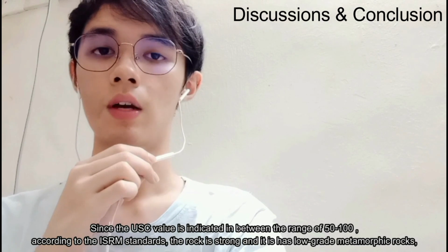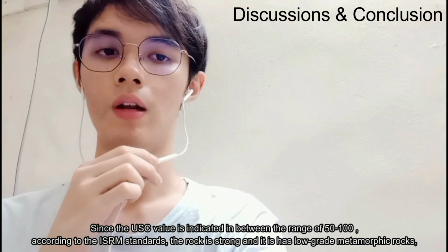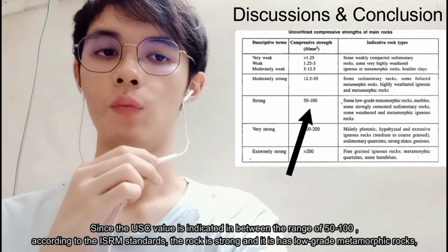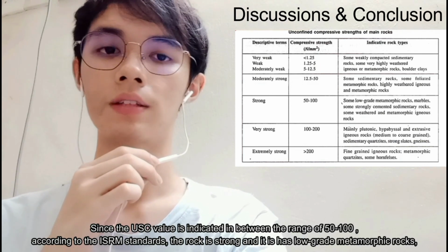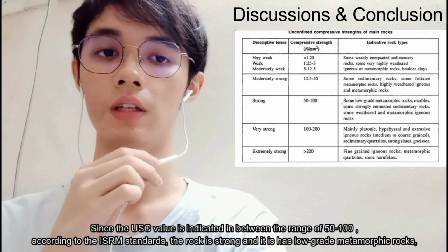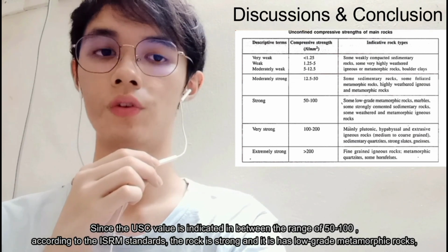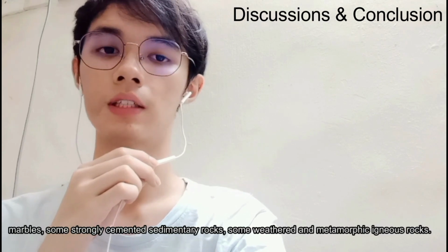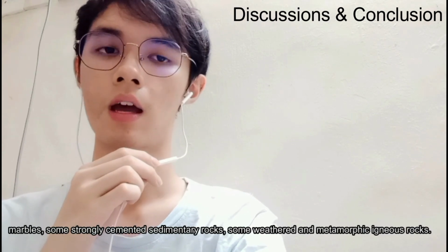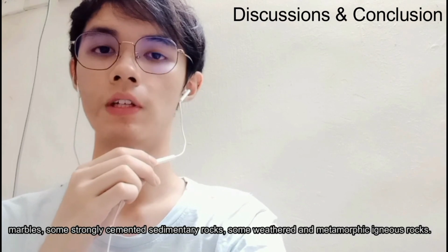Since the UCS value is between 50 and 100 Newton per millimeter square, according to the ISRM standards, the rock is strong and it includes low-grade metamorphic rocks, marbles, some strongly cemented sedimentary rocks, and some weathered and metamorphic igneous rock.